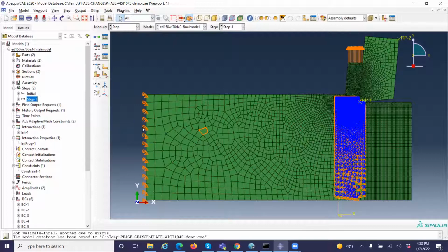This is where the material flows in from this side. And this is zone B, an Euler mesh constraint. And this is zone C here, this area. Zone C is a Lagrangian mesh constraint vertically, so it cannot move vertically. Zone D is here, on the chip. This is an Euler mesh constraint vertically. So we have 4 zones here.